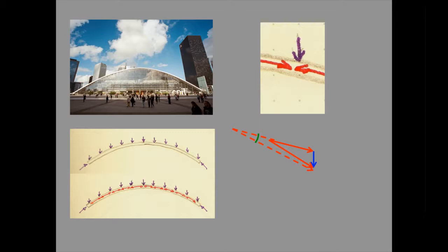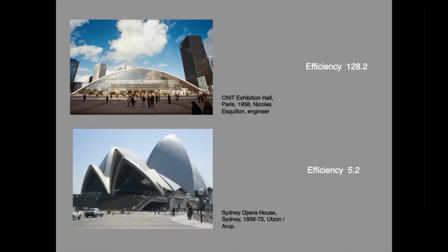A very important consideration here is that to achieve an internal force that is pure axial compression, which is the necessary condition for high efficiency, the shape of the shell is not a free choice for the designer. It is determined by the basic physics of the system, specifically by the effect of gravity on mass. This is the significance of the structural archetype, which is the shape that preserves the axial internal force only condition.